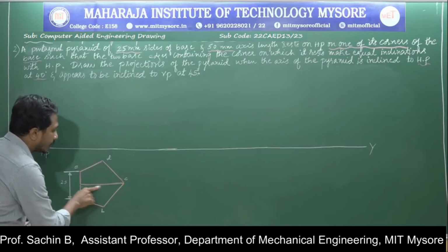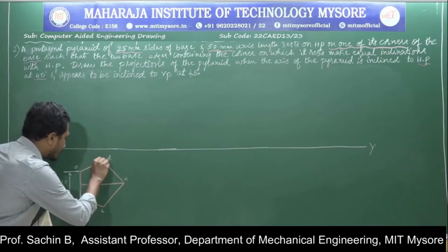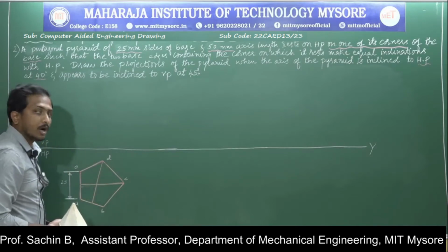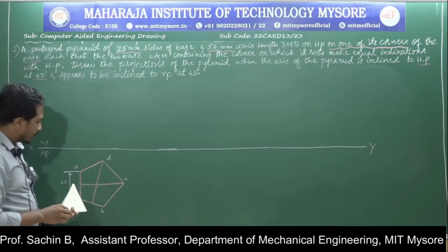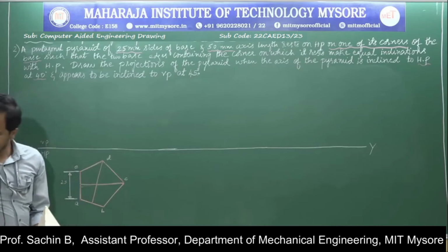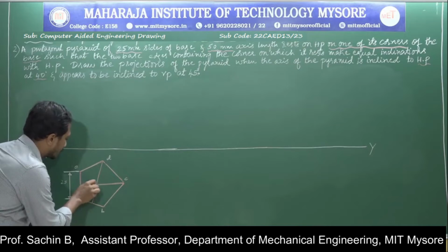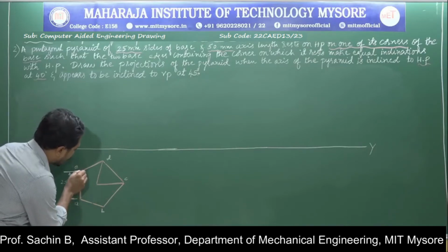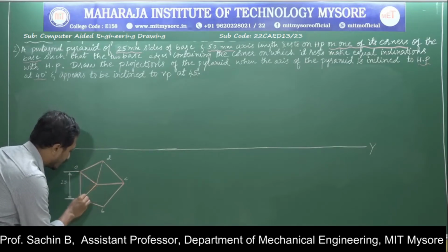To find the midpoint of the pentagon, again from point D to the midpoint of edge AB I am drawing a thin line. You people have come across how to get the axis there. Now this is the axis point. From there I am going to rub the lines that are connected to the edges. Now this is my axis point. To that point, from all the corners I am drawing the slant edges that are connected to the apex.